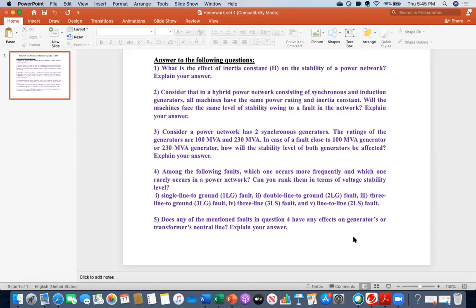And what will happen? The issue is that typically the neutral line is installed based on some withstanding capability, some prescribed current capability, heating capability. So once zero sequence current starts flowing, definitely it will be heated up. And if there is enough heat, it might even burn out. So therefore, the system will be floating, your generator or transformer, because it does not have a neutral.